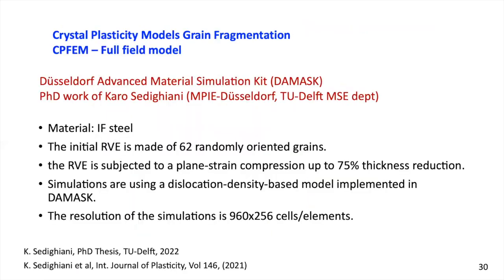Another type of model is in fact the work of Caro Sedigiani in his PhD at TU Delft. He works with full field crystal plasticity finite element models, and this work is far too extended to present here. In this approach, you do not consider the microstructure in a statistical representation, but you work with what are called representative volume elements.